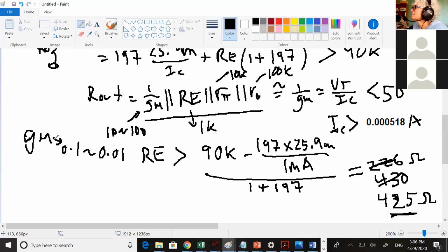Thank you, Professor. Okay, is that okay, Amani? Yeah, I think so. I'm just going to make sure I got to the part where, for the small signal model, we just had R out in parallel with R emitter, after you do the simplifications on it, but I didn't get to any of the math yet. Okay, the current source doesn't disappear. That's where this 1 over gm comes from. So check that out. It's not just RO in parallel with RE. A lot of groups got that though. Okay, I will double check that. Okay. Thank you.